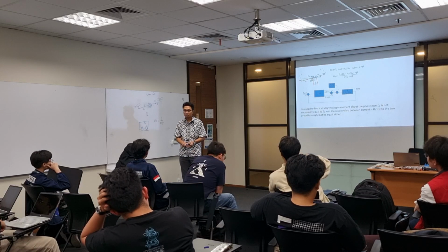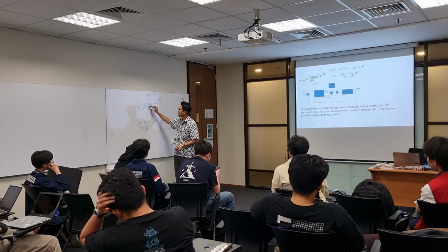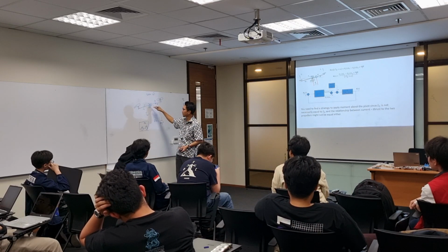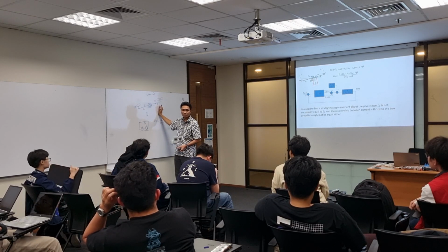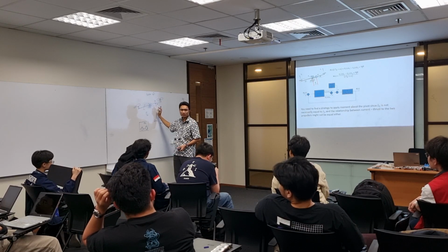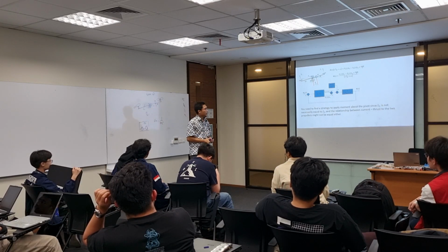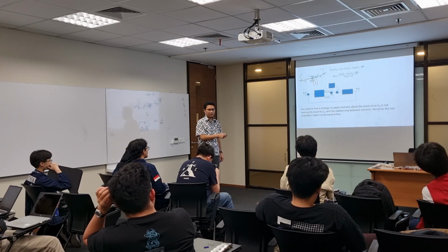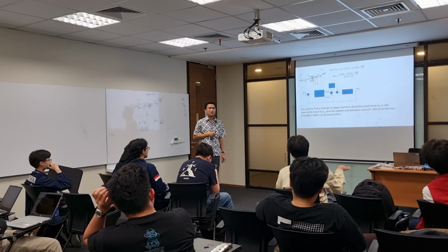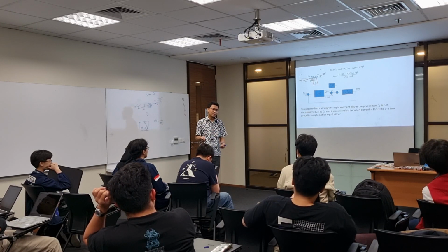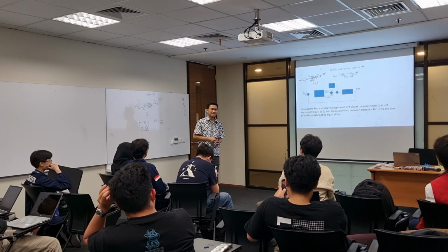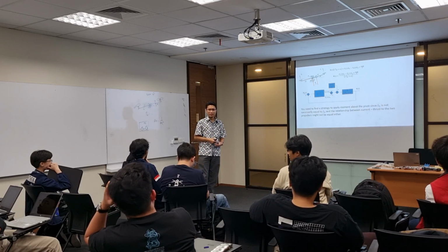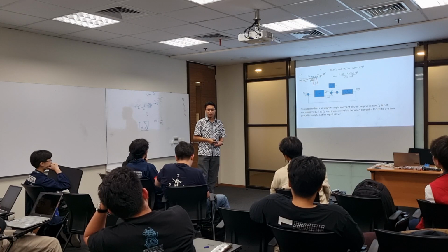Also, you will install an encoder here, so that you can measure theta. You can get the value of theta. You want to control theta, right? You want to regulate this, so you have to be able to measure theta. Not necessarily 0. Let's say you want to make it 45 degrees, or 30 degrees. It depends on the purpose.